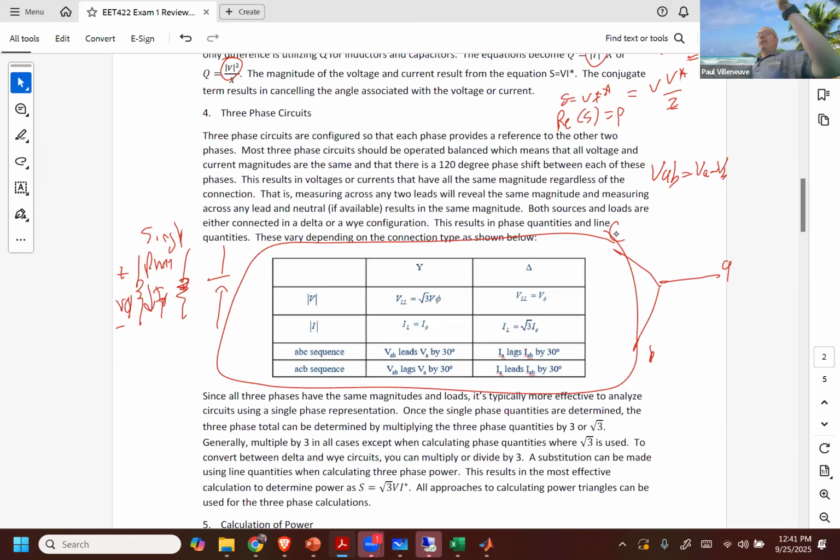So you have a red lead and a black lead. The red is on the positive and the black is on the negative. So it is subtracting the 2 points to actually calculate a voltage. So when you go VAB, red is on terminal A, black is on terminal B, and it's looking at a difference. So if you wanted to write that, that's VA minus VB.